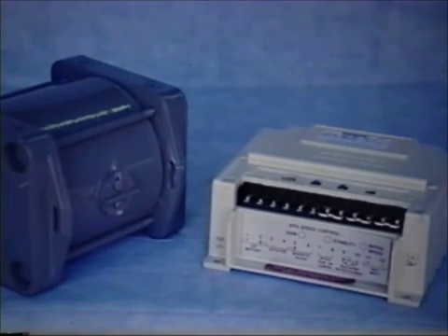A second factor affecting voltage is rotative speed of the alternator's shaft. If the non-regulated or self-regulated alternator's prime mover is equipped with a good governor, the resulting system, alternator and prime mover, voltage regulation should be fairly good.